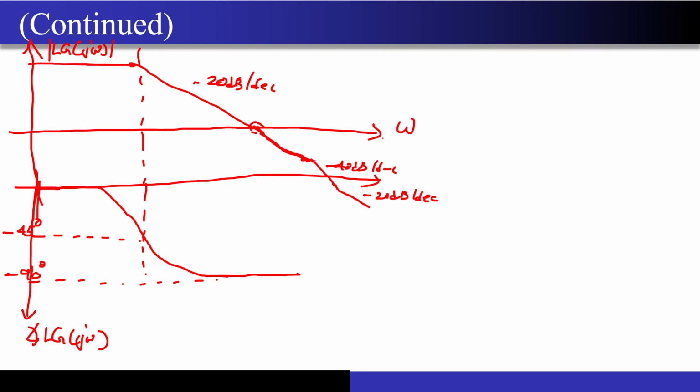So the phase degradation caused by this pole at this particular UGBW, I can ignore it if this parasitic pole 2 is at least 10 times omega UGB. If it is, let's say, 4 or 5 times omega UGB, then your phase margin will degrade, correct? This pole will have some contribution. But remember, how much margin do I have over here?